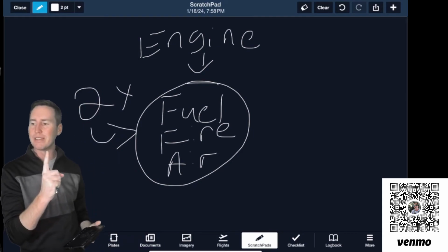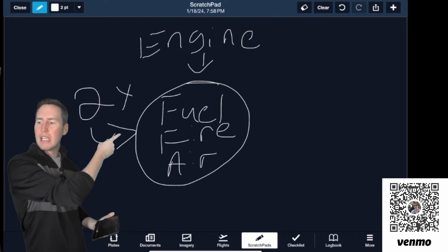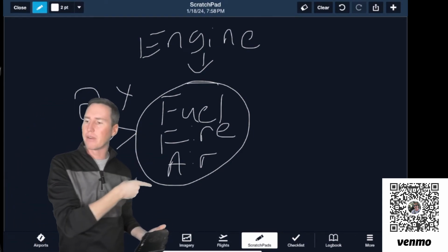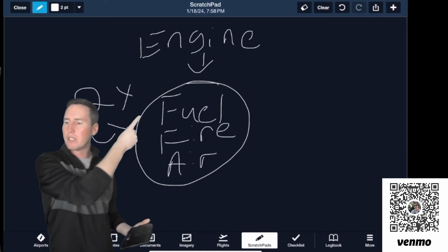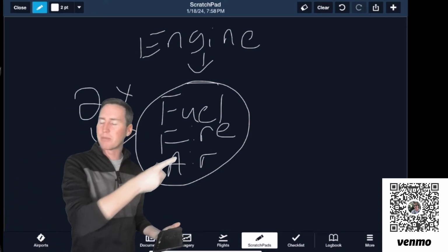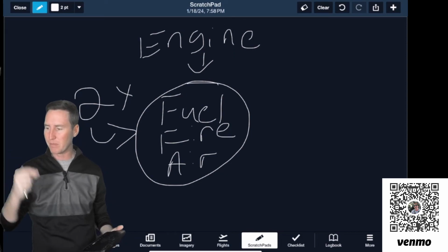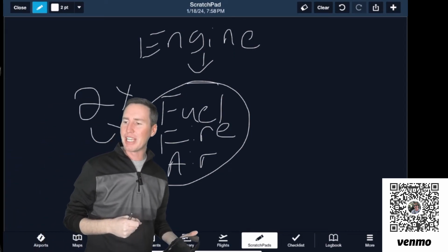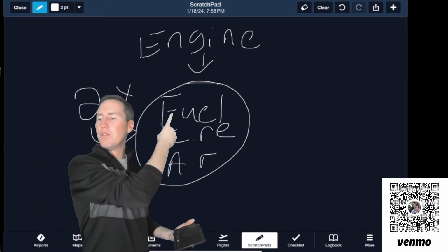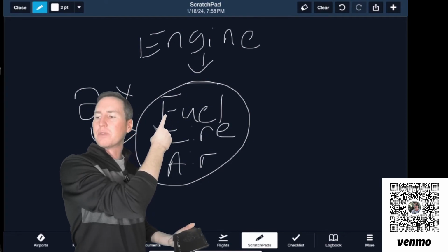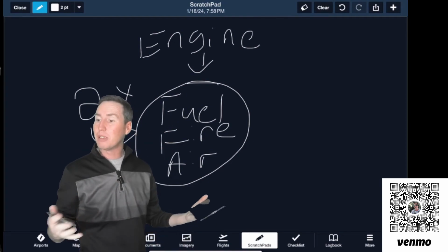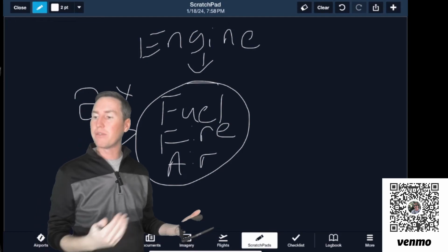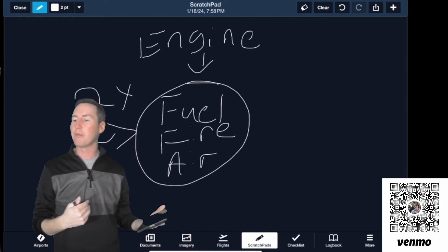Because we only have one engine, we need two ways to always have fuel, fire, and air to it, right? Fuel redundancy, again, I know I'm saying it over and over, but it's going to melt in your head, basically. Fuel redundancy is we don't really need a redundancy for gravity, but for the flow. So we have a fuel expansion vent tube for a primary vent.